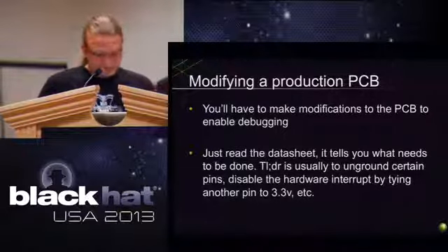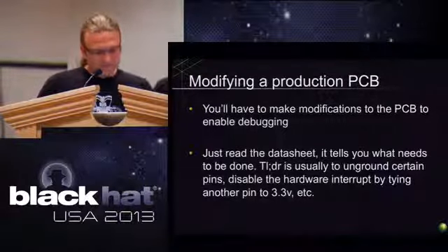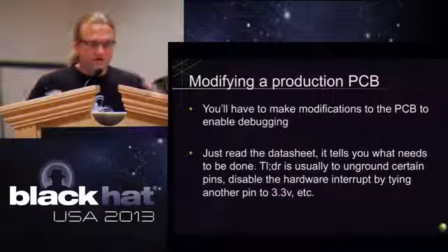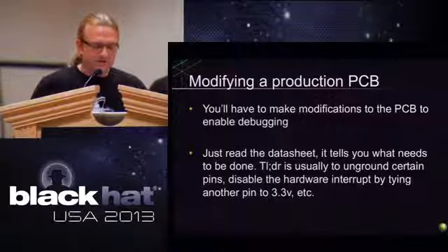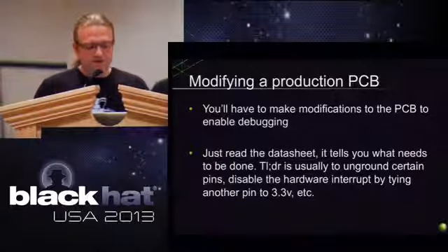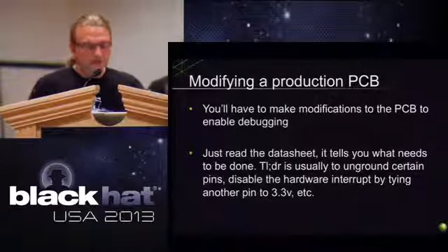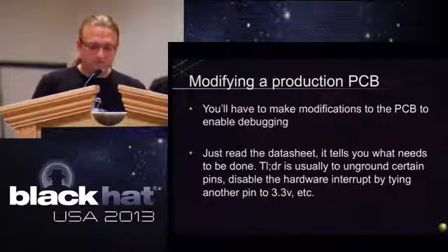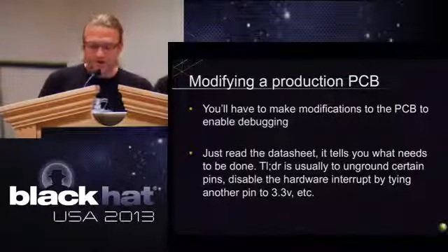Yeah, so typically what we find is, and this is just general, not really Teridian specific, but typically what we're looking for when we want to dump firmware is just to shift the chip into a different mode. So it's ungrounding a pin, grounding a pin, crossing a pin with power. These are how the hardware actually works. So this is what we're going for when we're really trying to understand.